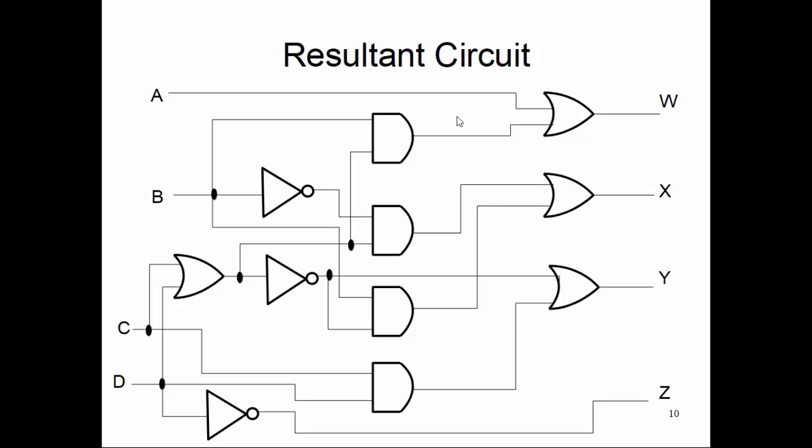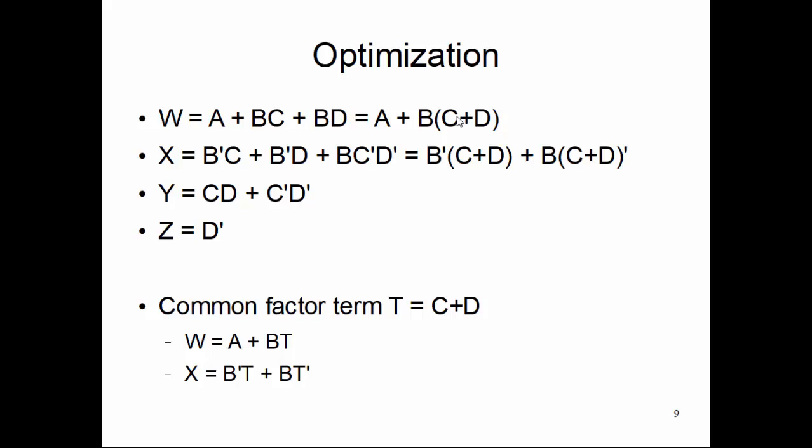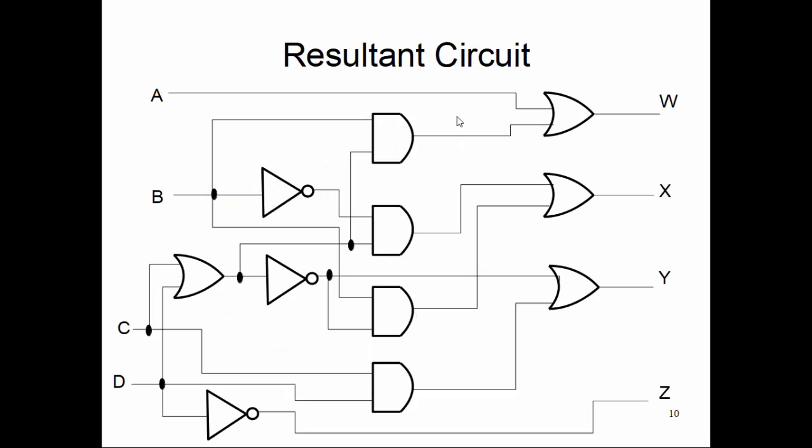So your circuit diagram represents your Boolean expression in a pictorial form, and now from here, since we know each of these gates, we can make them through electronic circuits, as we have seen in our logic gate lecture, that each of these basic logics we can derive from certain logic circuits. We can realize this on a piece of silicon, on which we can make some AND gates, some inverter gates, some OR gates.